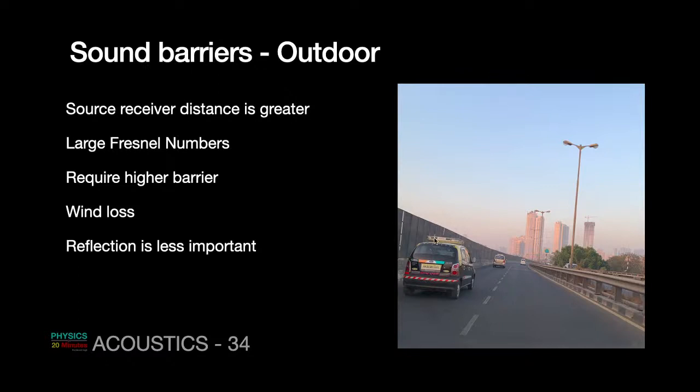So these kinds of sound barriers are often put up. They offer some protection from the sound, not a large protection. They are commonly overestimated. They are more effective at higher frequencies or at smaller wavelengths. Remember, Fresnel number was inversely proportional to lambda.